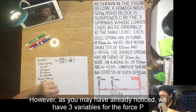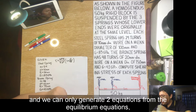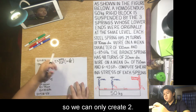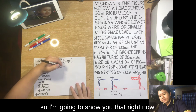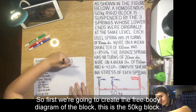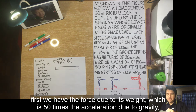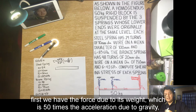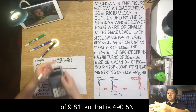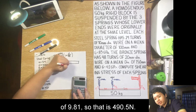However, as you may have already noticed, we have 3 variables for the force P. We have P1, P2, and P3, and we can only generate 2 equations from the equilibrium equations. So we can only create 2. I'm going to show you that right now. First, we're going to create the free body diagram of the block. This is the 50 kilogram block. First, we have the force due to its weight, which is 50 times the acceleration due to gravity of 9.81. So that is 490.5 newtons.